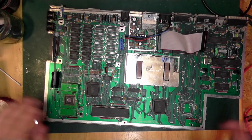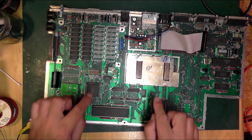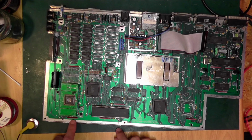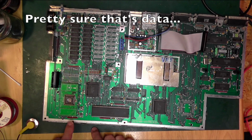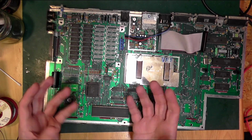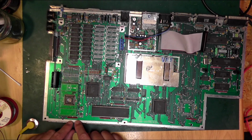I'm tempted just to reconnect things and make sure the machine still boots with one of its, did we decide it was a data line? I think we did. One of its data lines still, no, that's an address line, isn't it? I think that's an address line. That's coming from there. Yeah. So one of its address line blocks pulled up to 2.2.